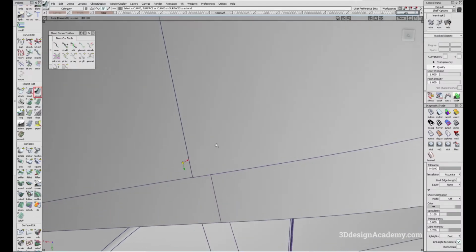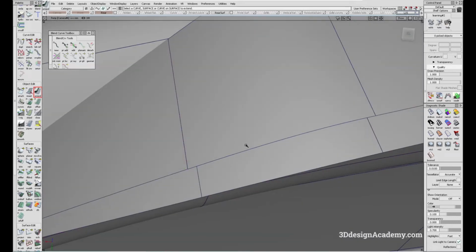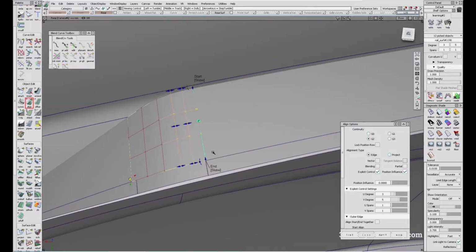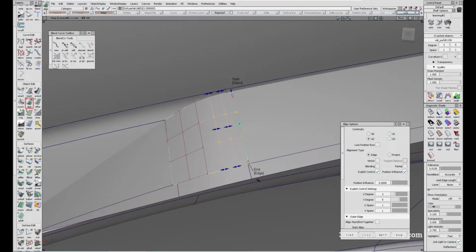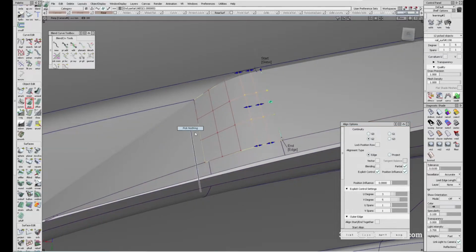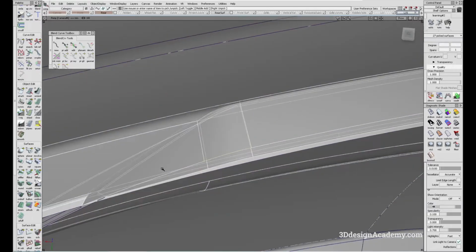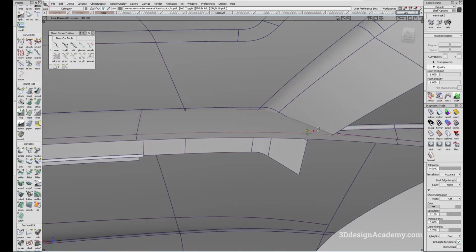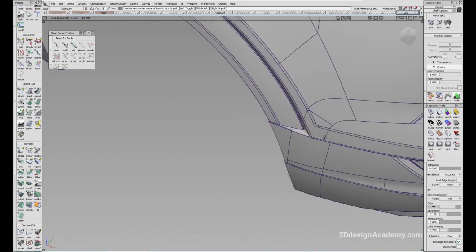Now the edges, it looks like it's not matching. So I probably want to do a little bit of refinement to make sure that it is aligned well. Okay, so I'm going to say partial over here. And I'm going to do the same thing over here. Partials on. It's edge on the other side, so that's good. Just going to delete the construction history over here, and I think we are ready to give it a fillet.